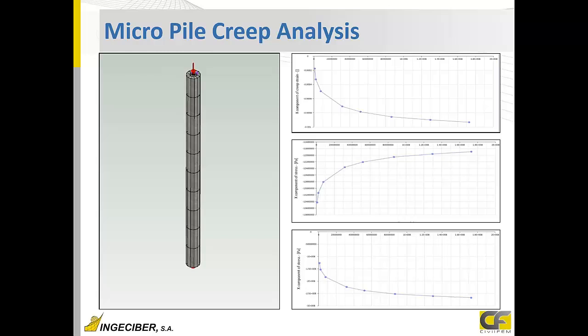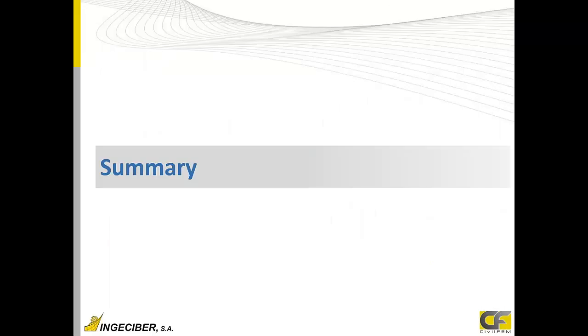The compression is creating creep and the tension is creating creep, so it's increasing deformation. Also, we can model steel reactions due to tension, so cracks will increase over time due to this behavior. So we can perform many nonlinearities together, contact, as we see, this insertion. CivilFEM is very powerful for combining all these types of nonlinearities and performing a really detailed analysis.